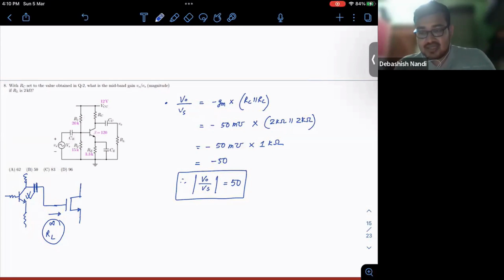So it is always taken into consideration how much the input impedance of the amplifier is, whether it is infinite or not. This is one of the reasons why MOSFET is preferred over BJT. One is that static power dissipation is almost negligible in CMOS circuits. Another is that input impedance is infinite in case of MOSFET. Suppose I need to amplify a signal 1,000 times.